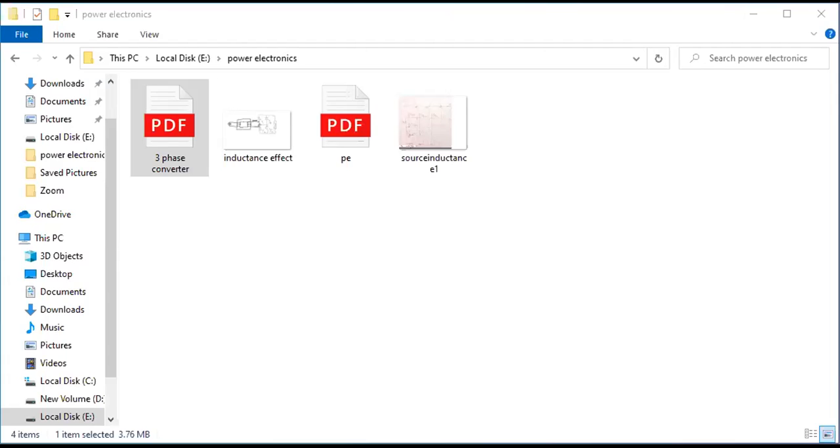Okay. So three-phase supply is actually a balanced system. Three-phase balanced systems are used for these cases, and the amplitudes of the three sine waves are the same, and the phase displacement between two phases will be 120 degrees. You can see this is the three-phase system. So this three-phase system has one neutral.